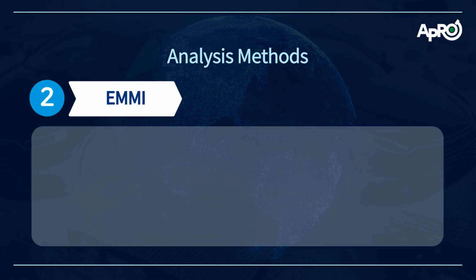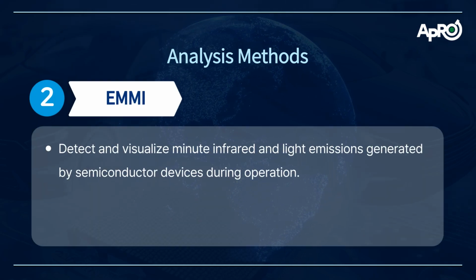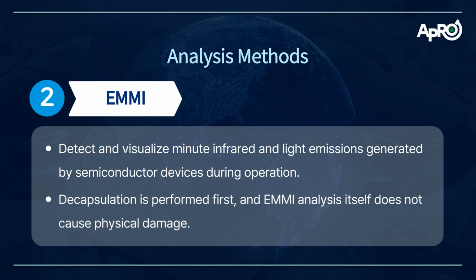Next, EMMI detects and visualizes the faint infrared and light emissions generated by the semiconductor device during operation, enabling the location of the defect to be identified. This method is classified as destructive analysis because decapsulation is required first. EMMI analysis itself does not cause physical damage.